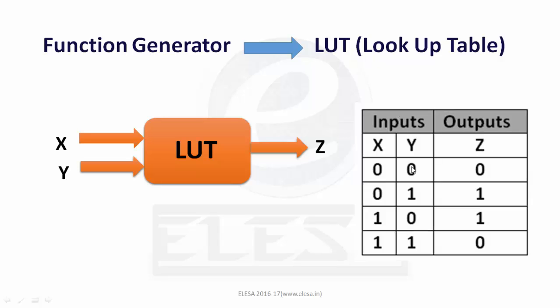With the help of a hardware description language like Verilog and VHDL, you have given all the information about your gate, that it is a two-input gate, it will have one output, and when 0 0 is applied, the output will be 0. When 0 1 is applied, the output will be 1. All this information you have provided by writing it in the code language, that is in Verilog or VHDL. So the FPGA will know that there are two inputs, right? Because of that, it will have all the possible 4 input combinations and their corresponding outputs.